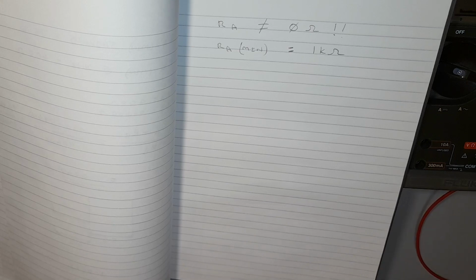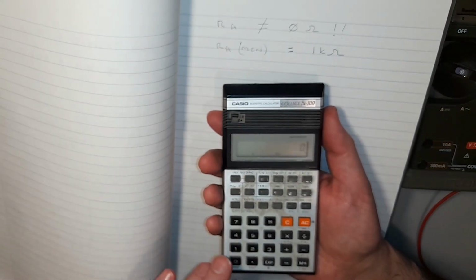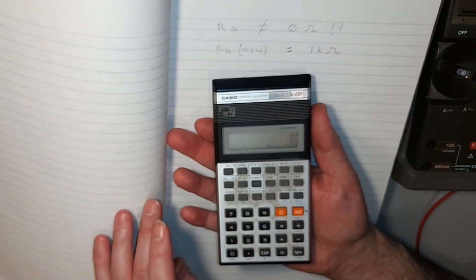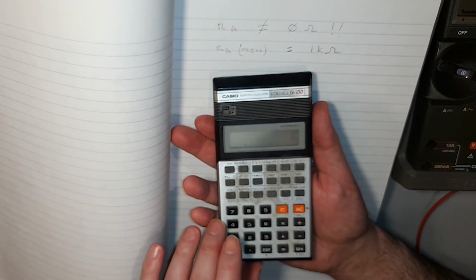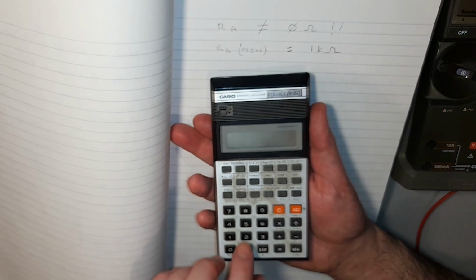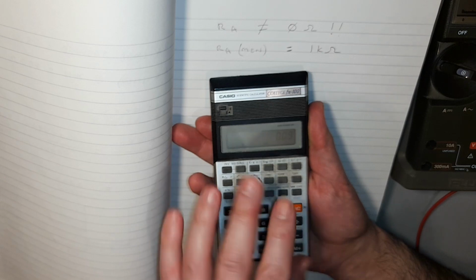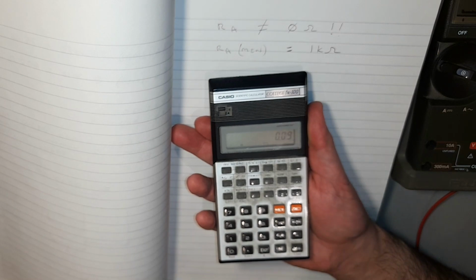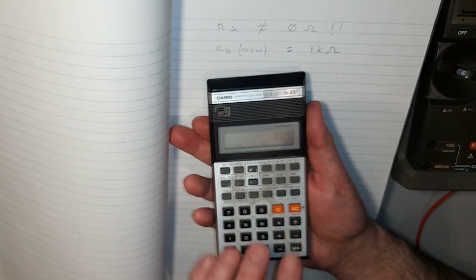I suppose we could do a calculation and say, well, if we've got 100 ohms, what's the current that's flowing? So with a 9-volt supply, I is equal to V over R. So 9 divided by 100. And that would have been 90 milliamps. Well, the chip is rated for 200 milliamps, so sourcing and sinking, but not on that input pin there. 90 milliamps, don't know. Maybe it survives that quite comfortably.